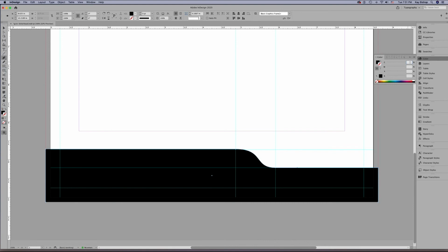And actually in this case I thought we were going to do the rich black, but we're actually going to do that later, and we're going to create a deep green color. So for the cyan, the C, I'm going to type in just the coordinates in the book, 85, and then hit tab. Then magenta is 50, yellow is 85, and black is 40, and hit return. So now we've got this color created.